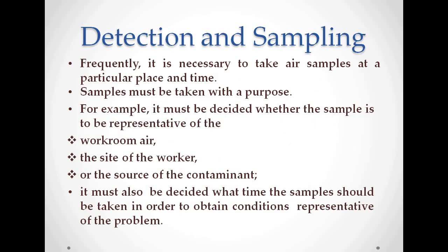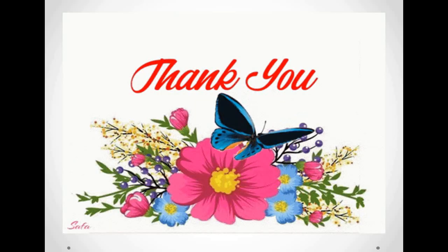Frequently, it is necessary to take air samples at a particular place and time. Samples must be taken with a purpose. For example, it must be decided whether the sample is to be representative of the workroom air, the site of the worker, or the source of the contaminant. It must also be decided what time the samples should be taken in order to obtain conditions representative of the problem.